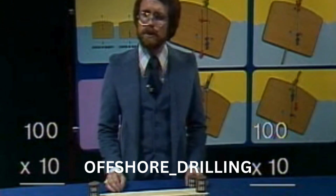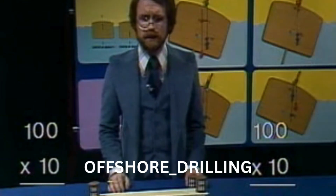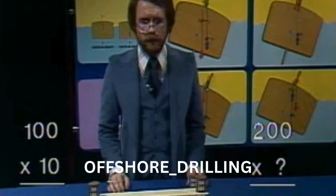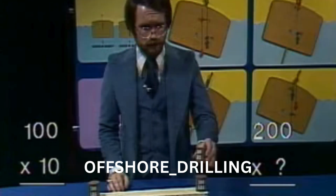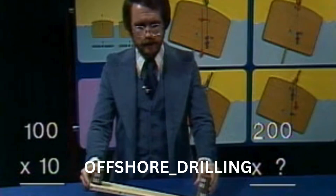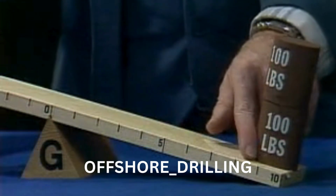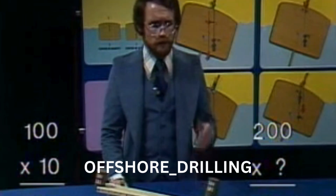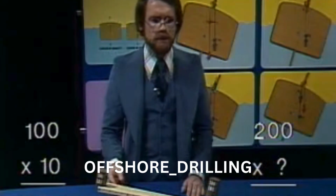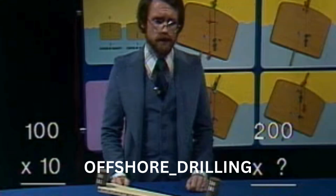Through a simple calculation, we can determine the exact location where the heavier weight should be placed in order to balance the seesaw. Let's assume that the weight on the right side of the seesaw is increased to 200 pounds. How far from the fulcrum should the 200-pound weight be moved in order to balance the seesaw? We know that in order to balance the seesaw, the moments on the left side have to be equal to the moments on the right. Since the moments on the left are 1,000 foot-pounds, the moments on the right also have to be 1,000 foot-pounds.